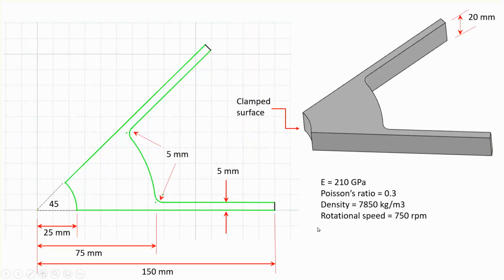Okay, so these are my dimensions, and one of the differences between the way I'm going to do it and the way it's done in that tutorial is that in the Abaqus CAE program, once you draw the sketch, you can actually make a circular pattern of it. That feature is not available in 3D Experience. However, instead of a circular pattern, you can take this and rotate it eight times by 45 degrees. It is possible to do it, but I will do it a different way. I'll create that sketch and create the part.